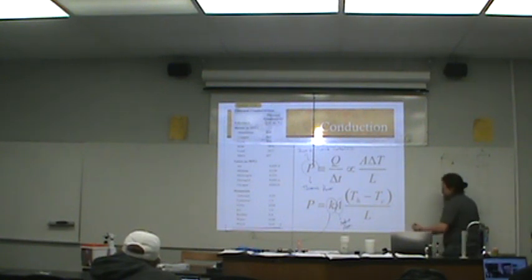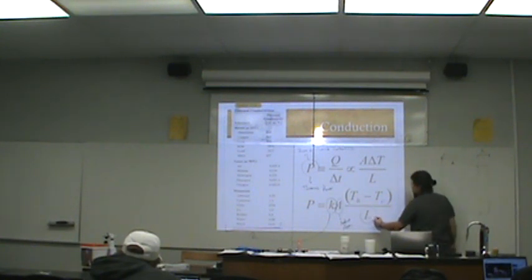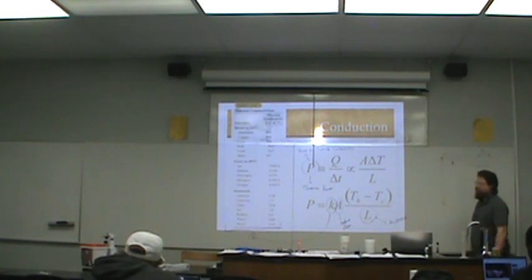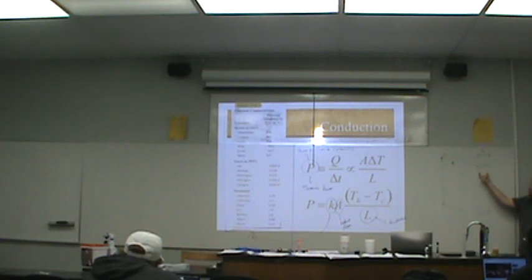I already talked about this factor. The depth, the thickness of the wall also matters. Call it L for length, but I prefer to refer to it as how thick the material is because it literally is the variable of how far the thermal energy has to travel to get from one side to the other.